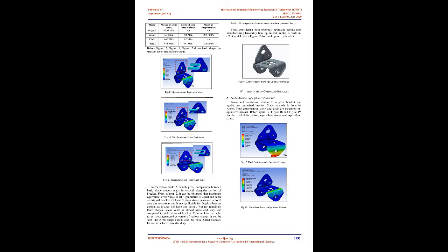Step 2. Define objective. Objective is to minimize the compliance. Step 3. Give response constraint. We want to optimize 20% of bracket mass. Hence our response constraint is to retain 80% of mass. Step 4. Solution. Topology optimization runs various iterations to reach the final solution. Below Figure 11 shows the topology optimized bracket result generated by Ansys. Fig. 12 Topology optimization result from Ansys.